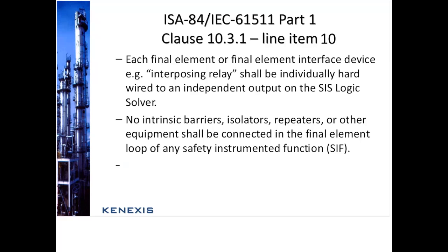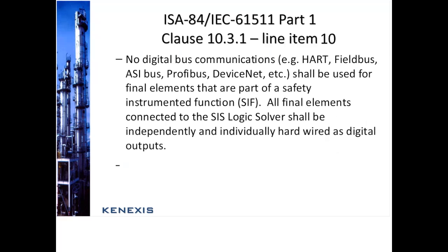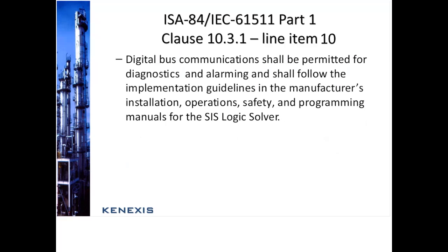No digital bus communications, HART, fieldbus, etc. shall be used for final elements that are part of a safety instrumented function. All final elements connected to the SIS logic solver shall be independently and individually hardwired as digital outputs. Digital bus communications shall be permitted for diagnostics and alarming and shall follow the implementation guideline in the manufacturer's installation, operation, safety, and programming manuals for the SIS logic solver.